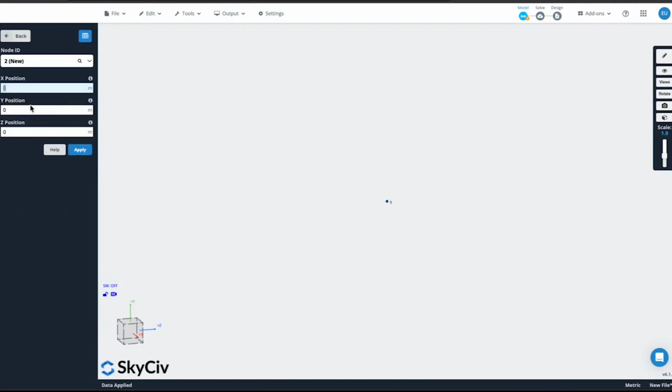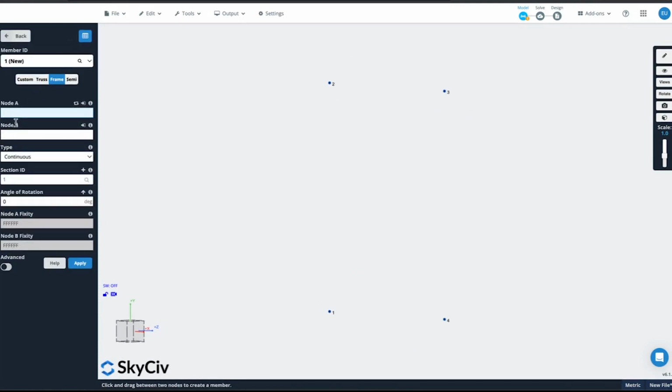So I'm going to have one at 0, 0, 0. We're going to go up, say, 5. I'm going to stay at 5. I'm going to go over 5. And then we're going to come back down, so we'll keep it at 5. So we're basically kind of drawing a moment frame this way. And so for the members, we're going to define it going from 1 to 2. We're going to define one from 2 to 3. And then one from 3 to 4. So we've kind of created this moment frame here.